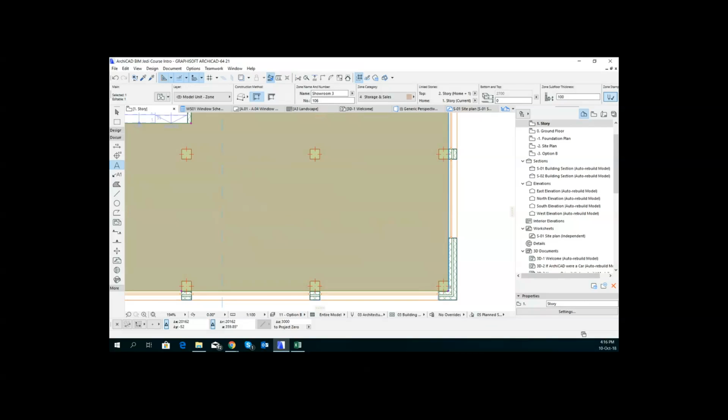and it can cause all sorts of problems, especially late in a project. Well, if you know that you've modelled up your walls and everything nicely and cleanly, it's fine. But we tend to work here by putting the zones first and then the walls, which then causes all sorts of problems. If you're putting the walls first and then your zones, you could then automatically tell them to fill that space. And then whenever you move the wall... But you have to then be precise. If you adapt a wall or anything, it has to be spot on. Otherwise it all goes. It's a bit of a pain, but yeah.